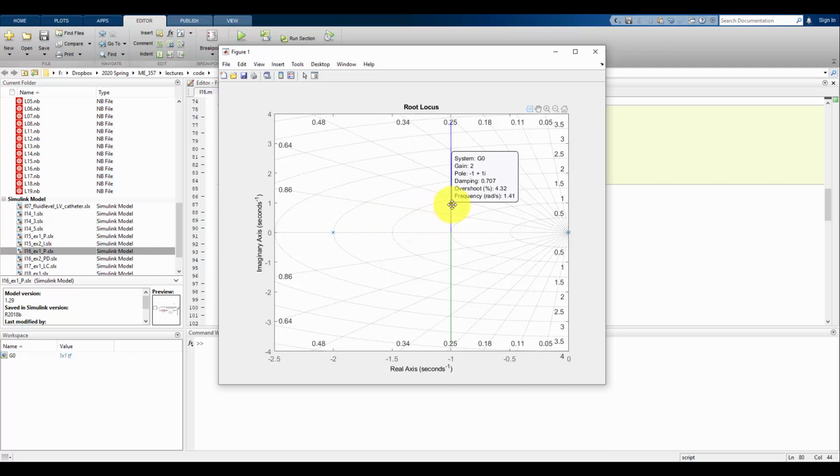If I could just take this point, if I could go to the left here, I'm going to barely change what my damping ratio is, but I'm going to be able to increase my natural frequency. Or if I can go to the right, I could decrease my natural frequency without really affecting the damping ratio. But again, those points aren't on this root locus.